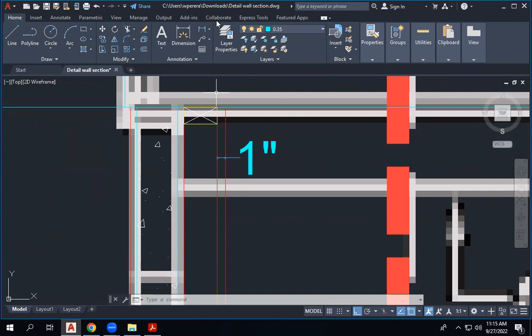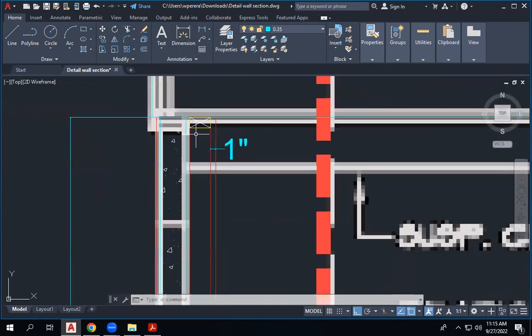Yeah, if you can select it, but the other thing is you can put it in notes. That's okay, but you leave it as 4-inch. This one, that gap should be given because it's done by us. Not the concrete wall, no need to give it. But now the concrete wall also we should give because it's an internal wall. So we need to tell the structural engineer that we need this wall not more than 4 inches. He can go with 3 inches or 2 inches, but not more than 4.